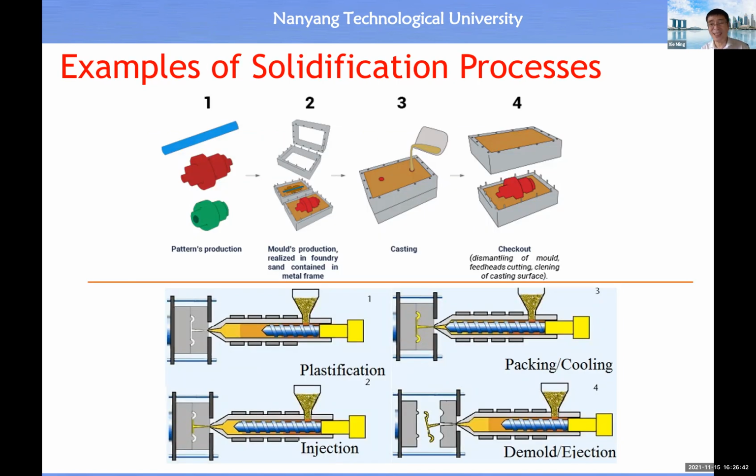You may have heard of injection molding. In injection molding, we inject liquid material inside the chamber of a die, then solidify it. We lower the temperature and let the liquid cool down to become a solid, then open the die, and we produce and finish the part.